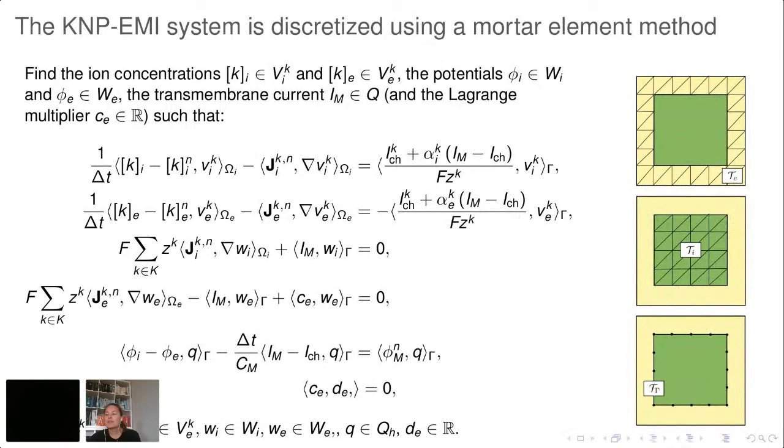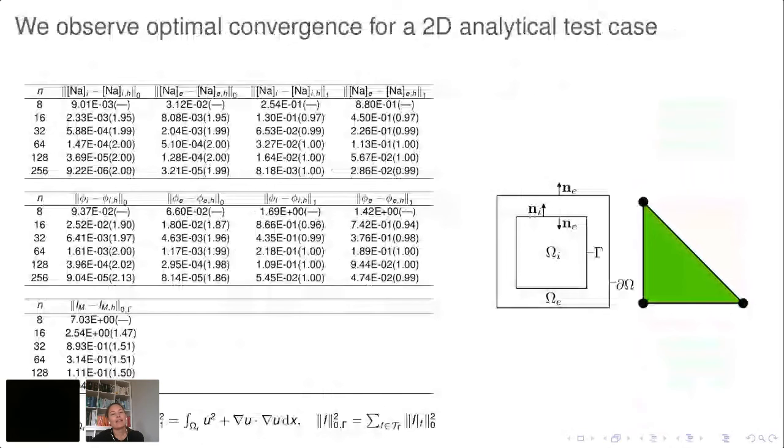And to verify this numerical scheme, we have calculated the errors and the convergence rates during refinement in time and space. So what we have done is that we have defined an exact solution and then adjusted the boundary terms, source term, and initial conditions according to the solution so that we know what we expect the solver to yield when we run it. And in this way, we can calculate the error.